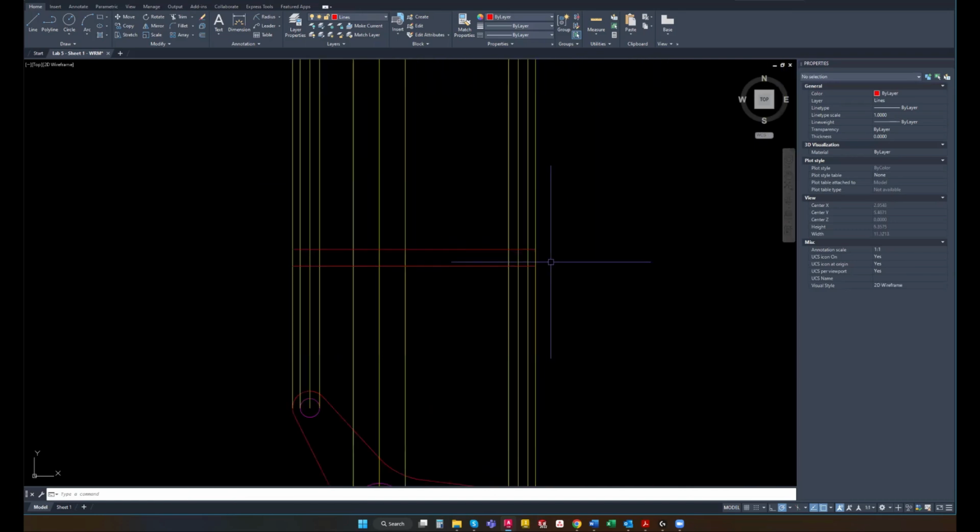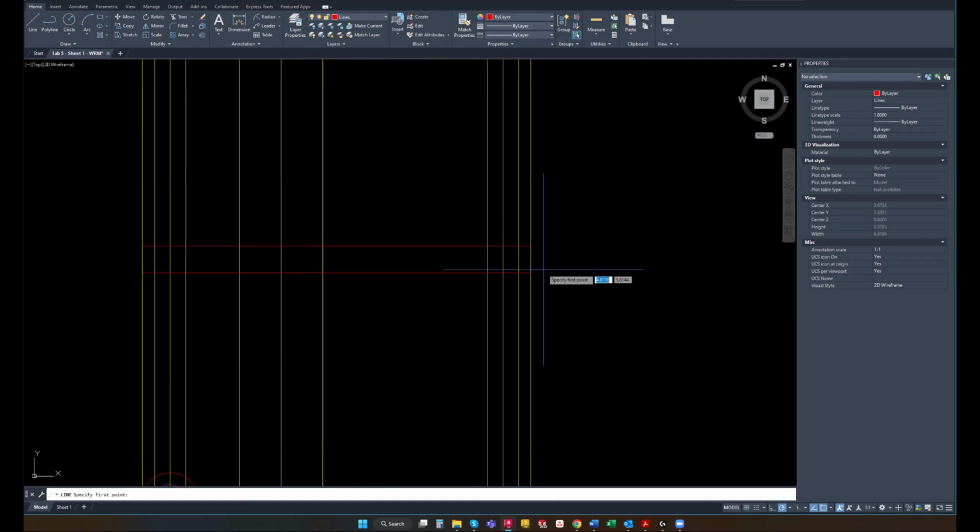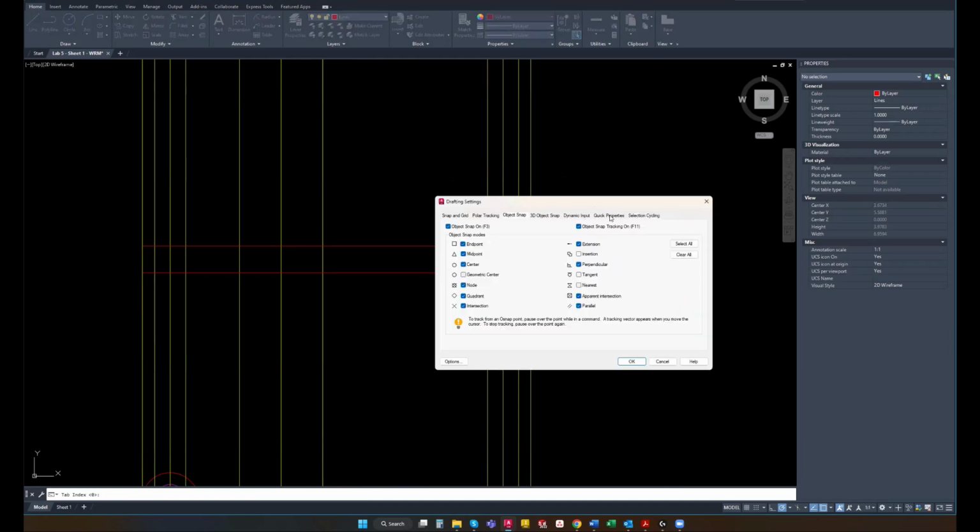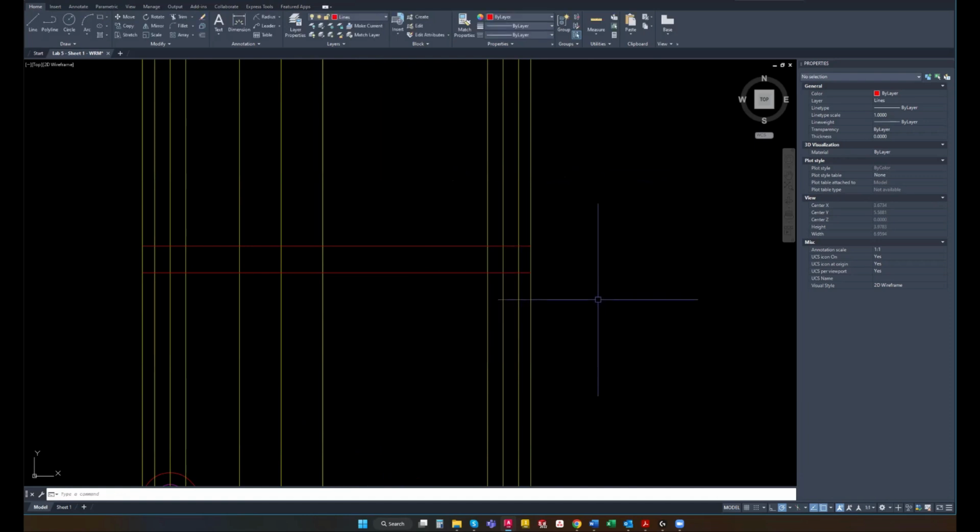And from here, we need to draw a line at 10 degrees. So remember, our polar snap should have a set that we can snap at 15-degree increments. So we could come in here to our polar settings. So just go to Object Snap Settings and polar tracking. So we can make this 10 and do it this way. So now we can snap just like that.